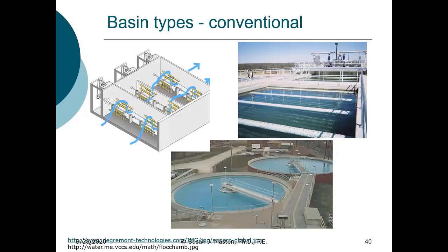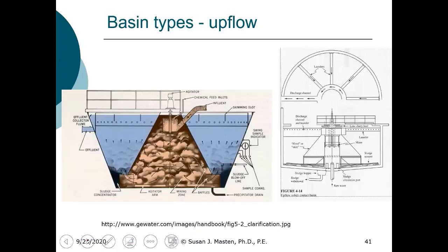And you can see this is an open tank, and it's hard to see, but in here are the paddle wheel flocculators. And then you see the sedimentation basins. We also often use an upflow clarifier. If we were visiting the East Lansing plant, as we normally would, we would actually see these in operation. And this is a rapid mix, flocculation, and sedimentation basin all in one unit.